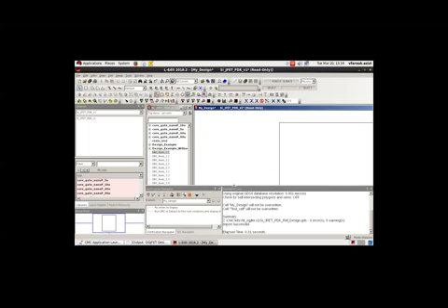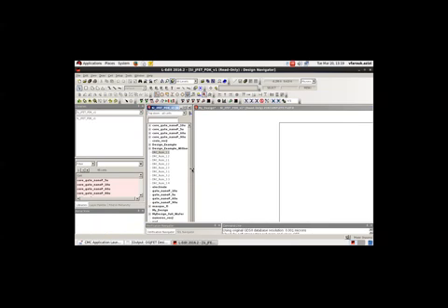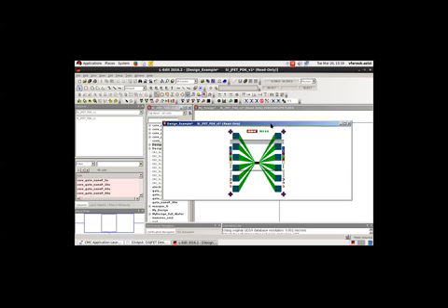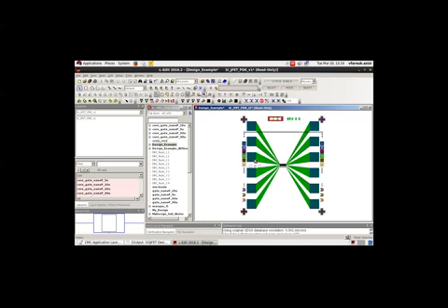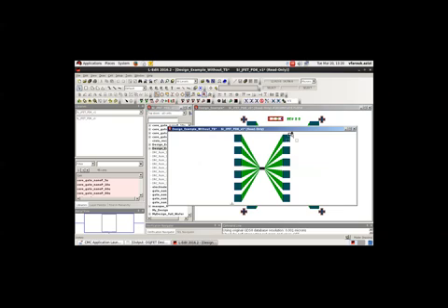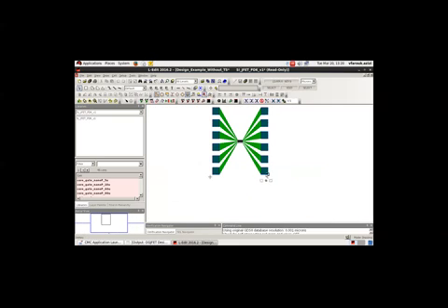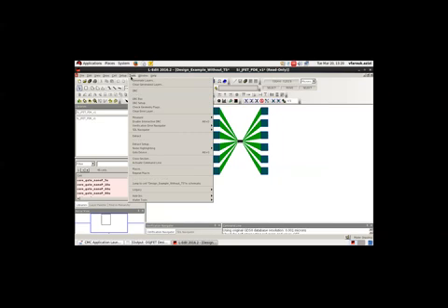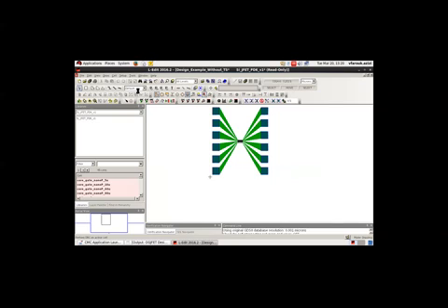And as you can see here, there are cells that you could use for your own design. The design example that was used in the reference design is here. You can see some test structures. These test structures are added by the fabrication laboratory, and your design will look like this when it does not have any of those test structures. You can apply this DRC, a Tanner DRC, to this design. And here, we can now run the DRC and check the design layout dimensions.